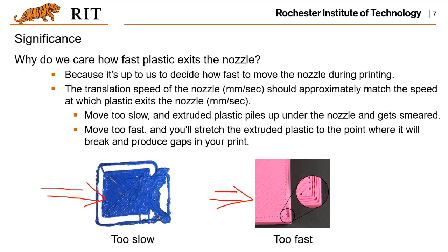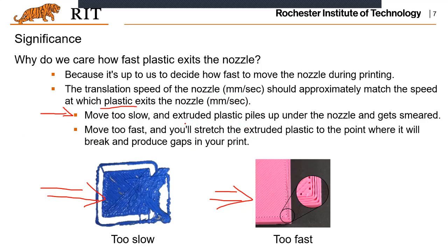That's really terrible, but you should understand the cause, because the speed of the nozzle movement over the platform is not matched with the plastic material exiting the nozzle, right?